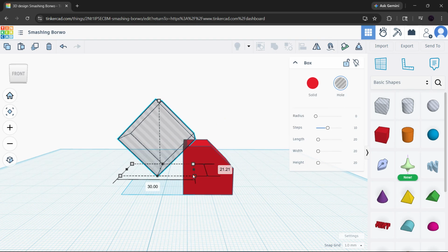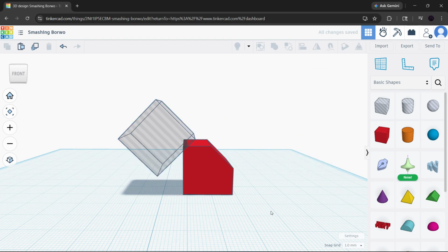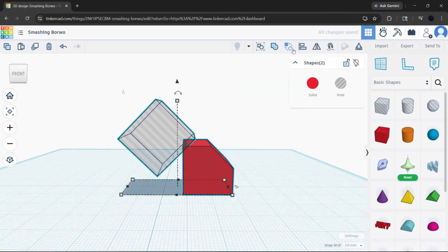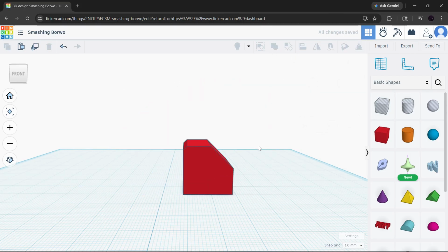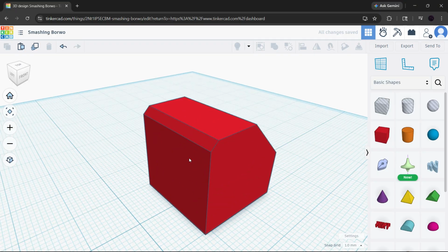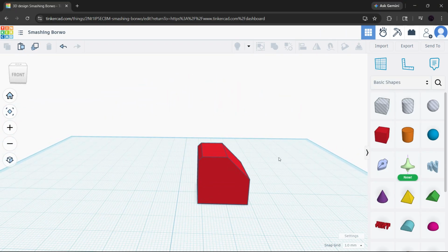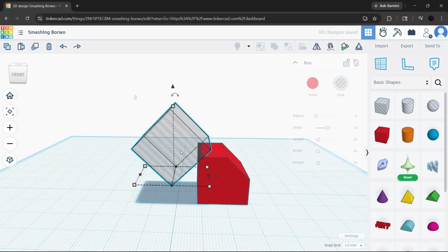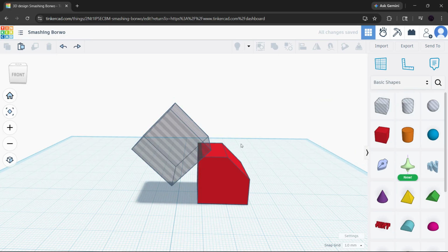If you want the bevel on multiple corners, just duplicate the hole shape and place copies where needed. You can do this by selecting the hole and using Ctrl+D to duplicate it, then moving each copy into position. This saves time and helps you keep all the bevels consistent. It's especially useful for boxes, panels, brackets, and simple mechanical designs where clean edge treatment makes the model look more polished. A few quick tips will help you get better results.